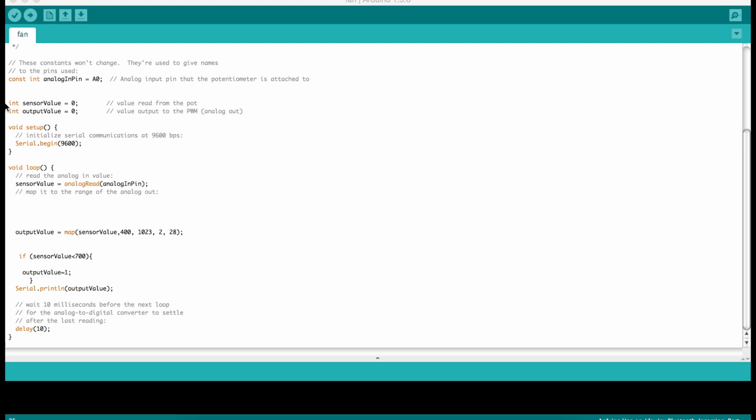What you're now currently viewing is an Arduino code which I modified, which was originally to control a potentiometer. The first bit of code here simply communicates with the analog port. Down here, the sensor values were new values which I had to put in to make sure that once the microphone was blown into, it would work. The Arduino has a circuit inside called an analog to digital converter that reads the change in voltage and converts it to a number from 0 to 1023. To find out what I needed, I ran a test in the serial monitor.